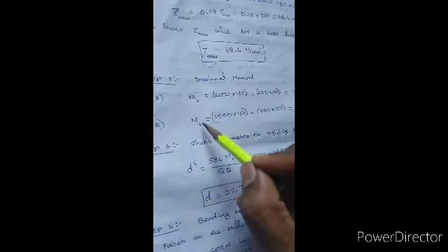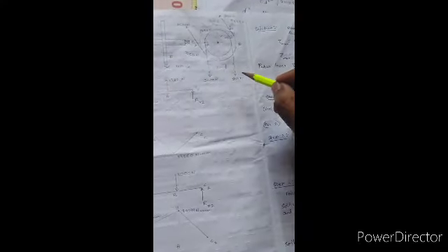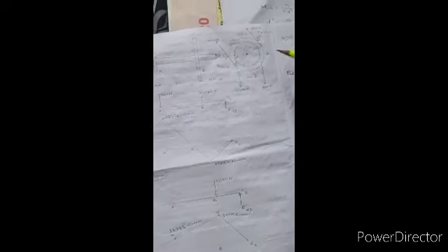If you take shaft B, there also you will get the same answer. But in the examination, take any one shaft, shaft A or shaft B. But you should know both load values. Suppose they give the belt, you should know the load acting on this side and the load acting on this side. So both the values you should know. If you know both values, you can directly find the MT value, for pulley A or for pulley B. If you find the value for pulley B, there also you will get the same value.